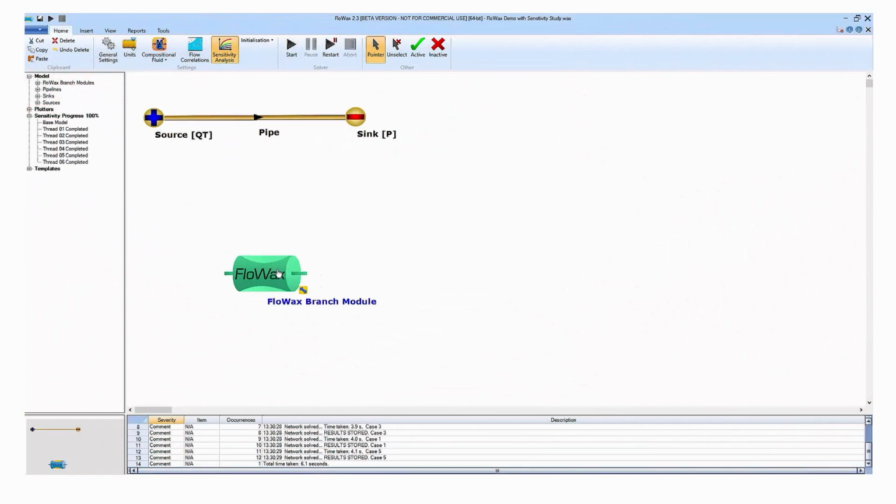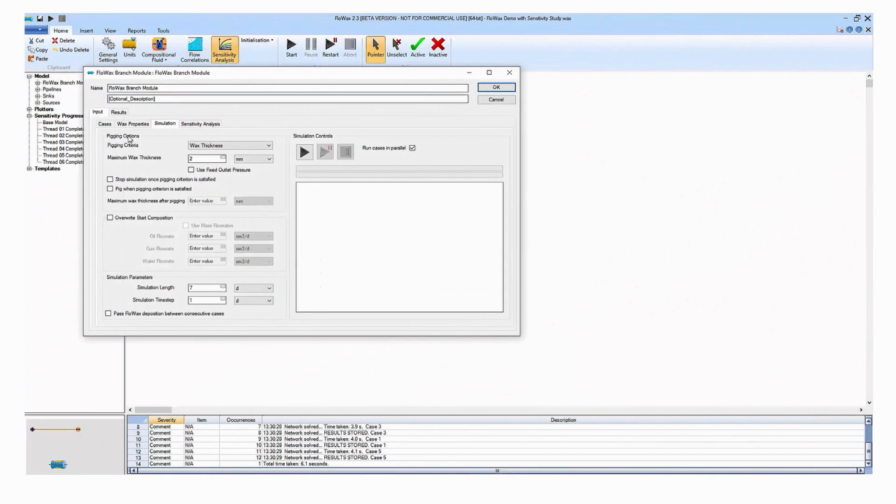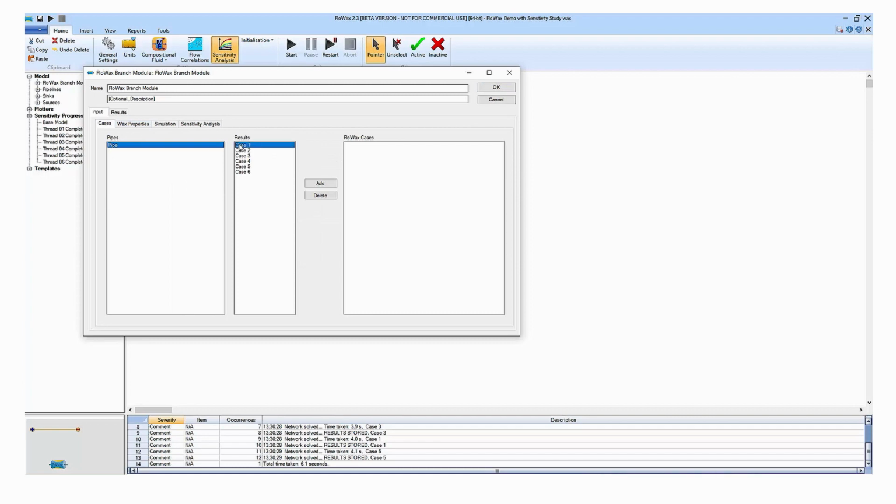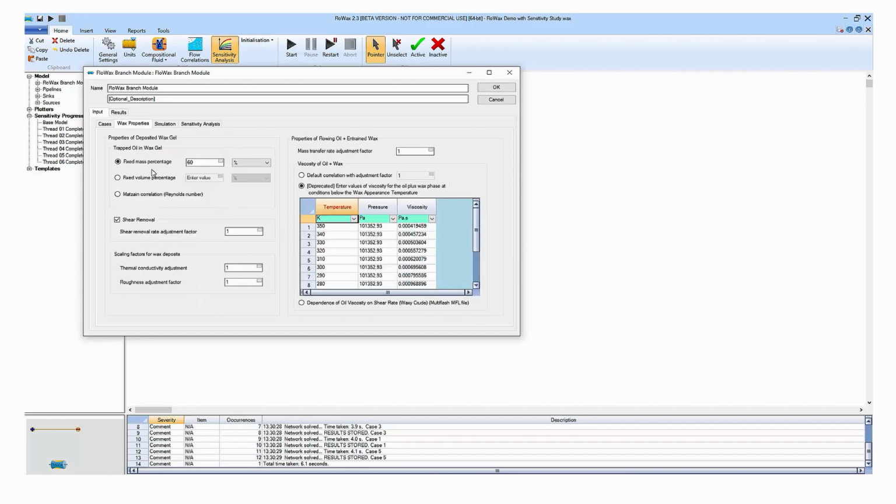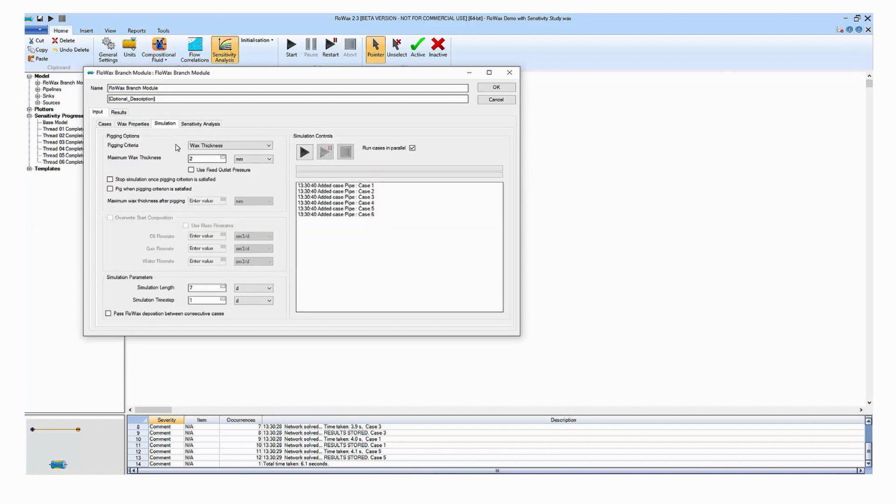In making decisions on modifying operating conditions, such as pressure or flow rate settings, or during a life of field simulation, you may want to evaluate the cumulative effect of wax deposit across the different cases. To model this effect, you can pass the deposit formed in the previous run to the following simulation, therefore allowing a progressive build-up of the wax deposit.